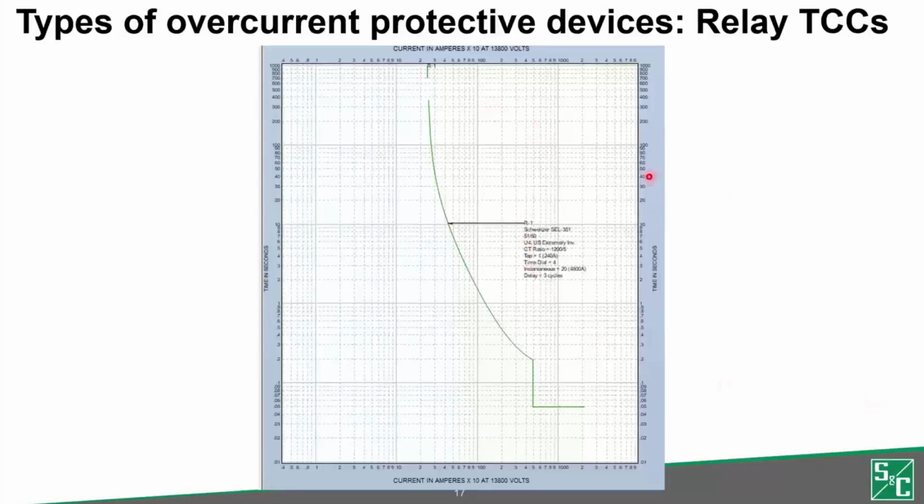Phase overcurrent elements need to be able to accommodate full load currents while coordinating with series devices upstream and downstream, and its settings and TCC can be adjusted based on these factors. Every relay has its own range of programmable pickup currents, its curve shape, and its time multipliers that can be adjusted based on its application in the system. Ground or residual overcurrent elements can be set in relays differently than the phase element to respond differently for ground fault current magnitudes.